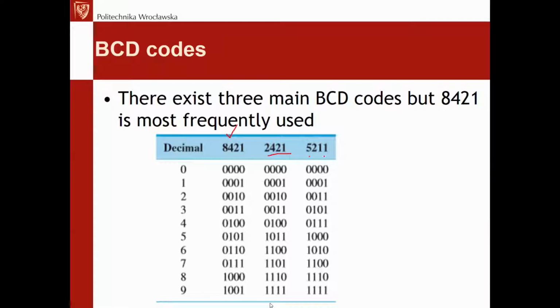Although, of course, be aware that this is not the only possibility in case of BCD, so there is a chance that sometimes during some project you will notice another BCD coding. But the standard one, the one that you must know, is 8421.